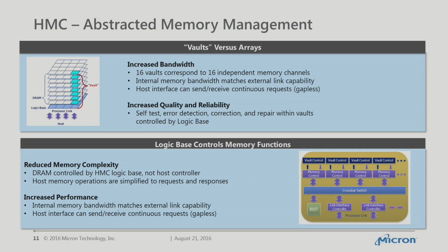Okay, a little bit of the details of it that I probably won't dwell too much on, but you can see in the graphic the basic 3D topology, the topological makeup of an HMC. And so we came up with a little new nomenclature. What you would call, let's say, a DIMM rank, a single rank, we now call a vault. And that vault, one piece of one DRAM will respond to a request.